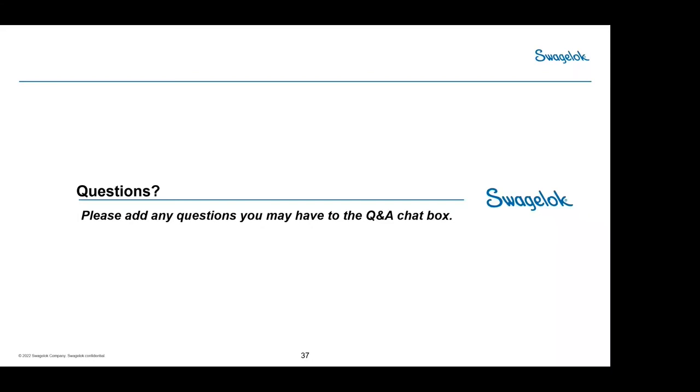Let me understand the question well. I know we talked about purging and how important it is. We focus a lot on the reaction gases when they are coming in. We figure out we're going to bring this gas, it is going to have this reaction, then it's going to exit, then we bring the next gas, and so on, continually. The factor driving purging is how fast you can get a gas out so that the next gas can come in. Unless there is a continuous flow of gases in and out, it is very difficult to know, when I bring the next gas, whether my previous gas is out of the system or not.